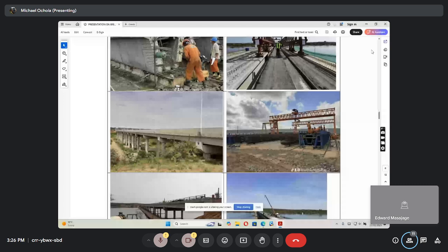Here now they're working on the deck. You can see they have a crane helping them to lift certain things, a concrete pump is there, and many more. We shall learn more. So this is the construction. But still the designer must follow, because you must check this construction to ensure that reinforcement spacing, reinforcement sizes, the grade, the shape of your girders, everything complies with what you have modeled and designed. If you don't inspect during construction, then they can make changes, and the behavior will be different from the design. That's why the engineer must pay special attention to site presence. So you are not detached from construction.